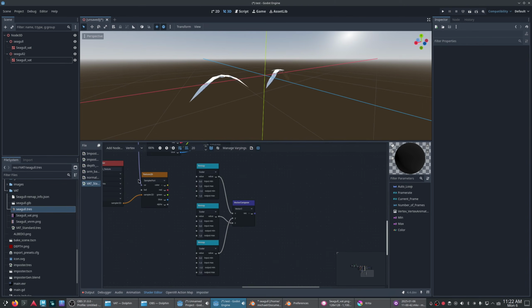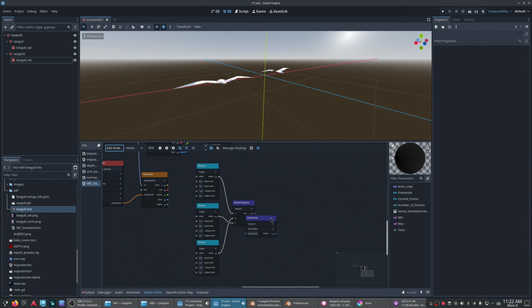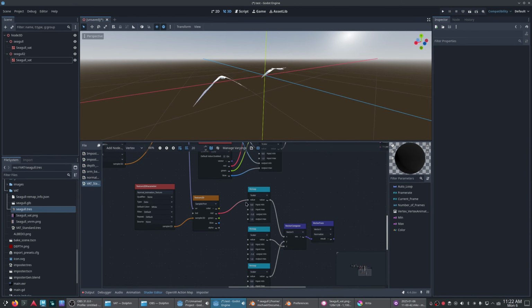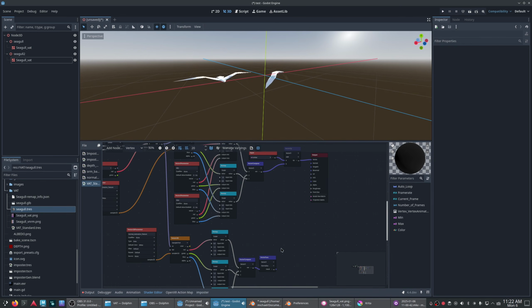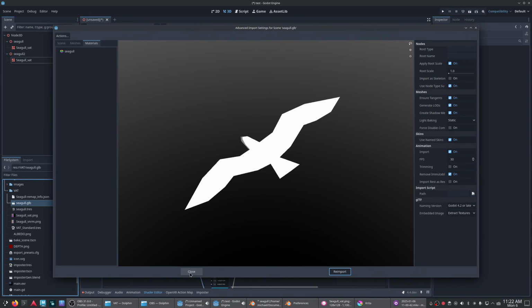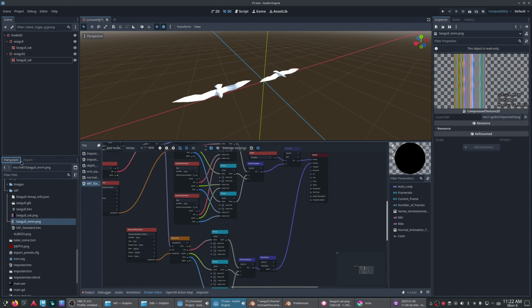And then at the end of that, we're going to make sure that that is normalized, just meaning that the length of the vector is 1. And we're just going to do that same thing, red, green, and blue of that normal animation texture. And we're going to plug that straight into the normal. And then now, if we make sure that our normal texture is hooked up correctly, which looks like it is, and that needs, like I said, same treatment, lossless, no bitmaps.